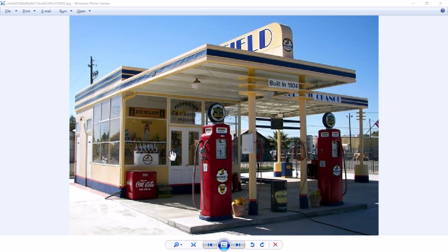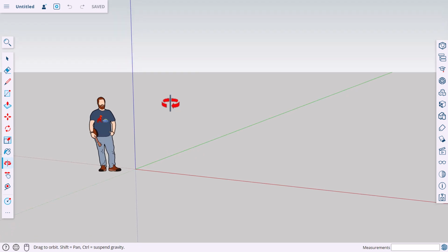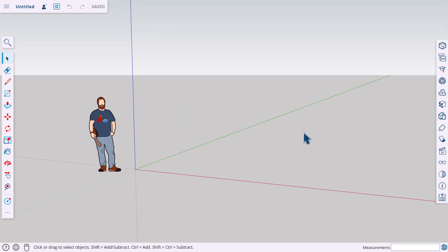And we are probably not going to find these in Revit City. You absolutely can search in Revit City and knock yourself out. But I wanted to show you a different way to bring in objects. Again, you probably have seen this before, and that's my old friend SketchUp. Now, I actually have the full version of SketchUp, the Pro version, so I don't need to use the web-based version, but I figured a lot of you may have just the free version. And that's okay too, because you still have access to the 3D warehouse.